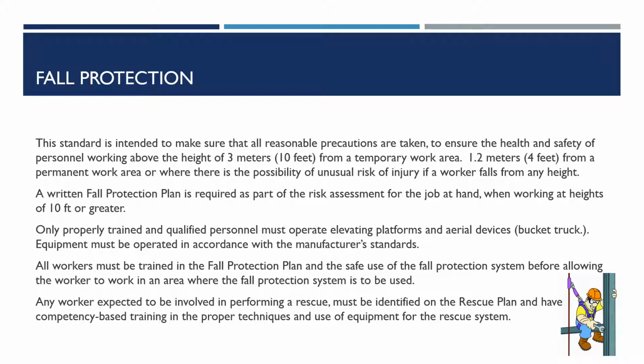Only properly trained and qualified personnel must operate elevating platforms and aerial devices. Equipment must be operated in accordance with manufacturer standards. All workers must be trained in the fall protection plan and the safe use of the fall protection system before being allowed to work in an area where the fall protection system is to be used. Any worker expected to be involved in performing a rescue must be identified on the rescue plan and have competency-based training in the proper techniques and use of equipment for the rescue system.